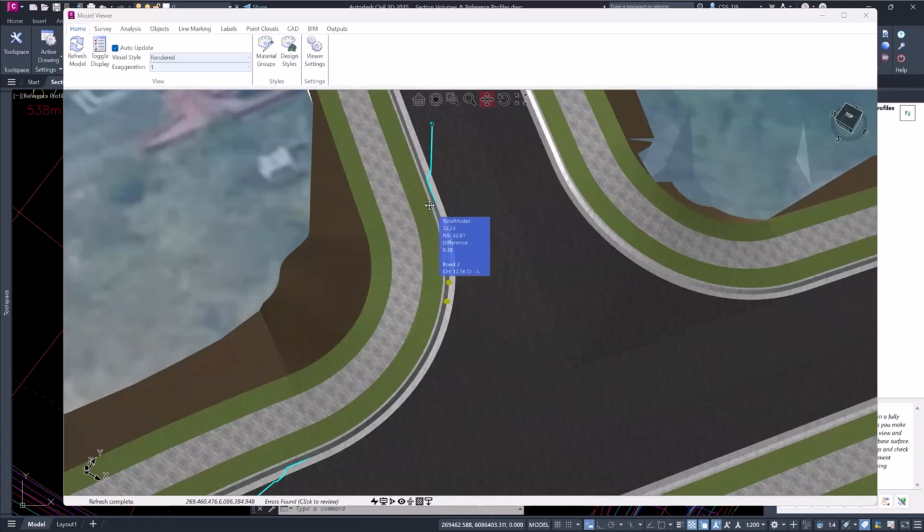Now, I can certainly regrade the curb return. That might be one solution, but it still requires me to set the levels of the incoming, outgoing parts of the curb return. So we'll need to modify, well, in this case here, it's the left edge of road 2, which I could have certainly done with my normal variations. I could use my varies and I could do some cross-form manipulations. I could use my string control, and then I'd actually have to go and apply that. So it's always this two-step idea. You make the manipulation and then you apply it. This is binding all of that together for you.